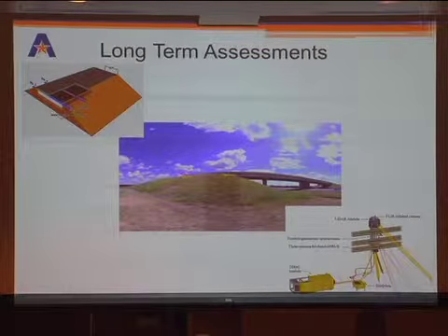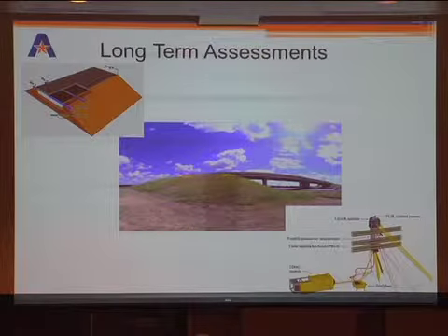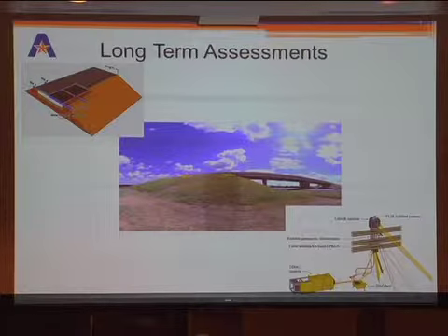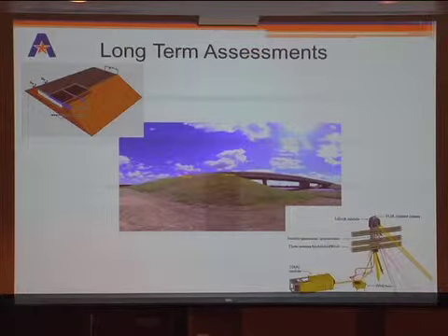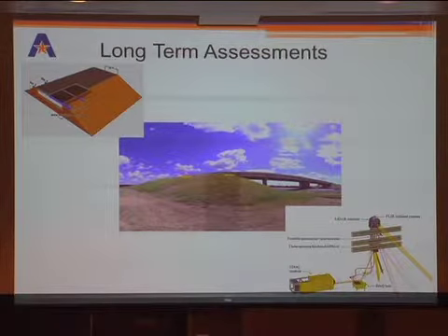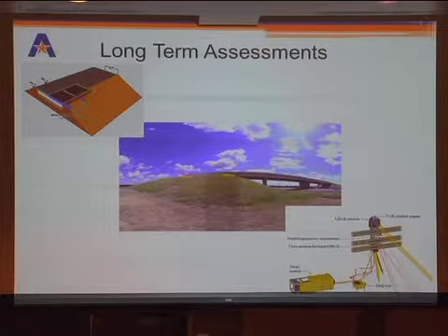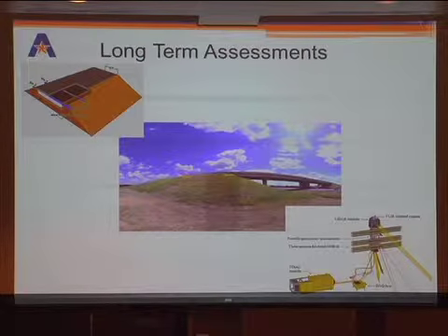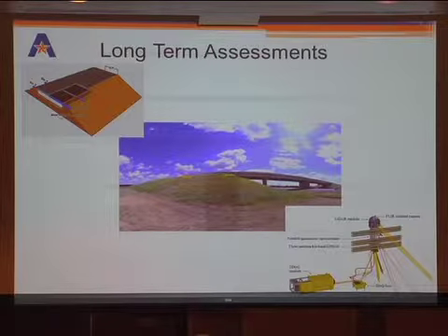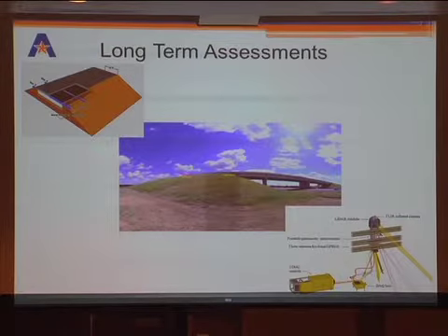In this current year of monitoring, we're also looking at the integrity of the whole system, because we put the foam in the middle travel lane right under the bridge area. On the sides we still have slopes, and we had significant rain in May. So we're looking at the data, using some LiDAR data, because we do see some side surface slope, since you're putting two different materials. We didn't slope the foam; we just stacked the foam right in the middle. If we could do a tapering, it probably would have been nice, but we know that would cost more. We didn't have that liberty in this particular project. But we learned from this project.